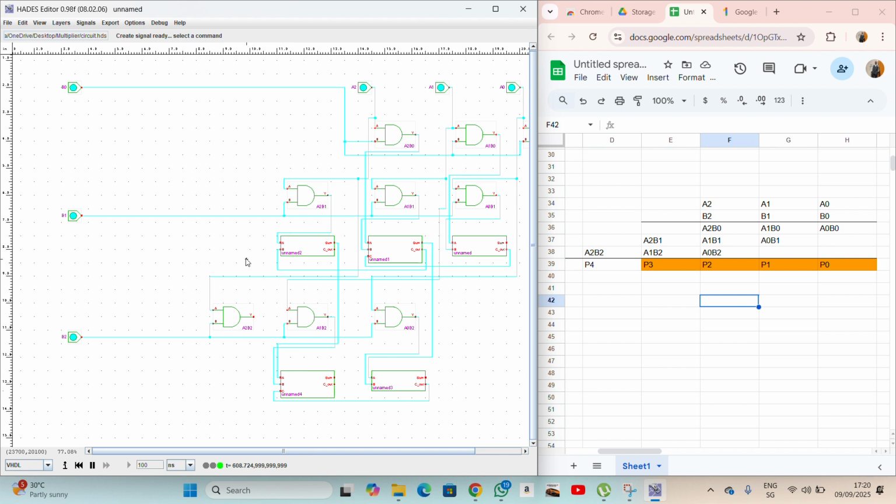We have two C outs that are being added to this variable, and it means that now we have a total of 3, because we have this variable plus 2 C outs, which is now 3 variables in total, and that's why we're going to need again a full adder. So I'll copy this and then I'll put it somewhere here. So I'm going to have the first C out, which is this. This here as the first one.